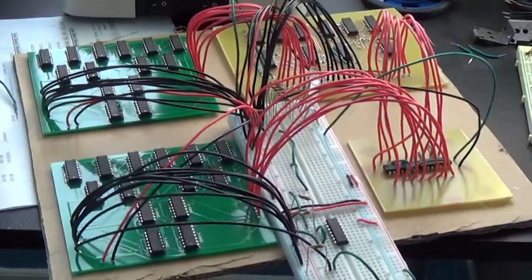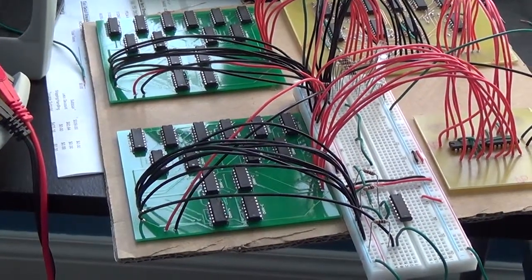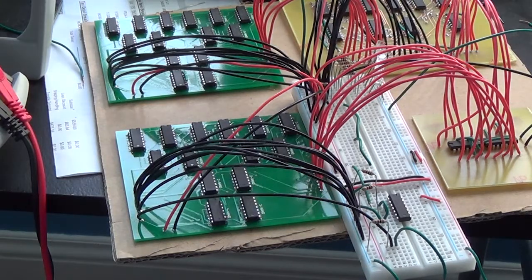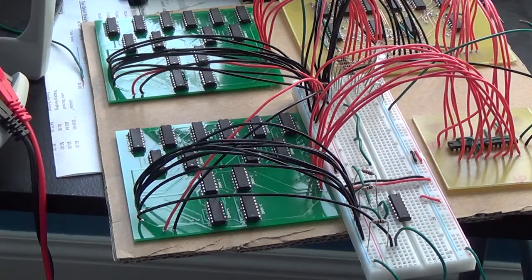So what I did here was I'm storing data on both of these registers, and I'm sending it through the ALU so we can see if the registers are storing data, and we already tested that the ALU is working. But I'm doing this in a fairly specific, interesting way, just to test this out. I have a constant value stored on this register, and right now I think I have it set as 3, but when I demonstrate this I'm just going to put binary value 1 on this register, and it will stay there for the whole demonstration.